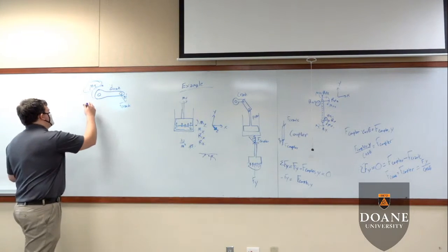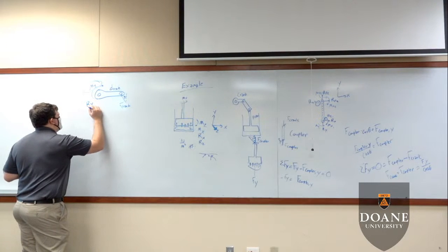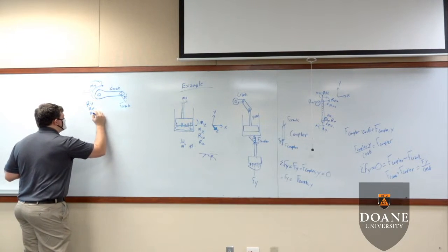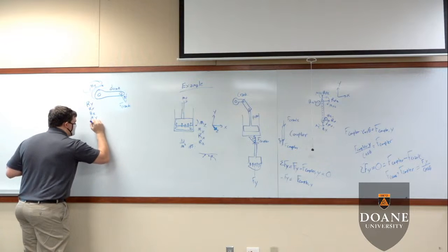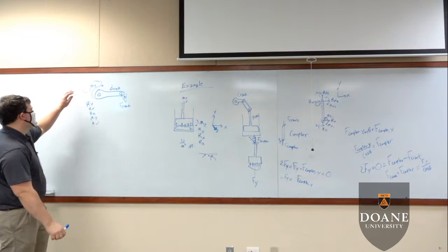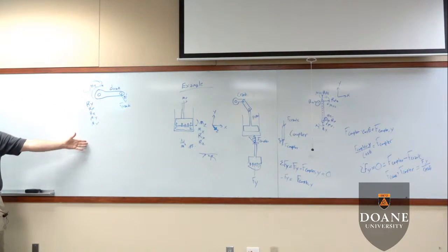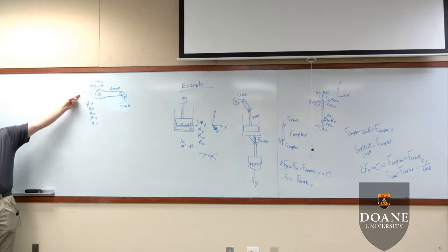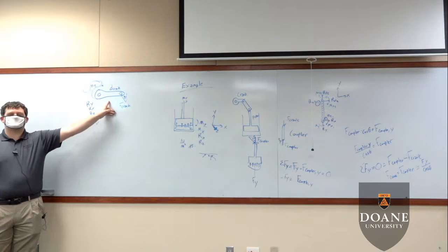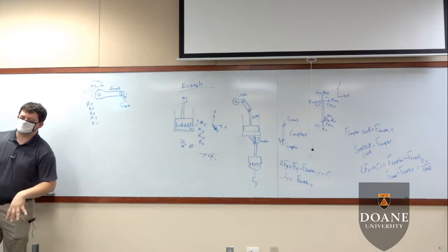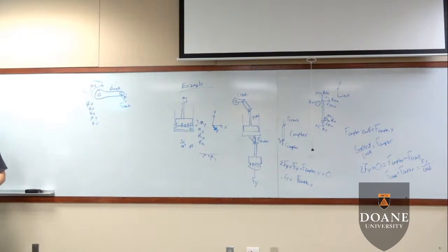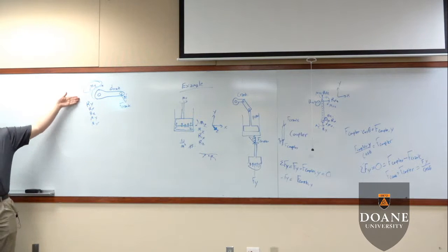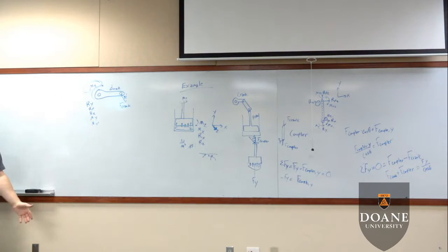The joint itself creates Ry, Rx, Rz, My, Mx values because it is a 1 degree of freedom joint. But we're transferring torque out of that by rigidly connecting this crank to an axle. Does that make sense? So even though this is a 1 degree of freedom joint, we have all 6 forces potentially present.